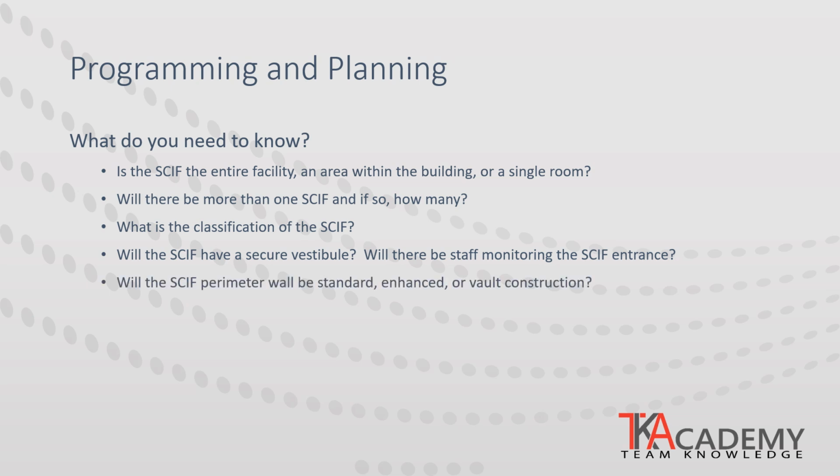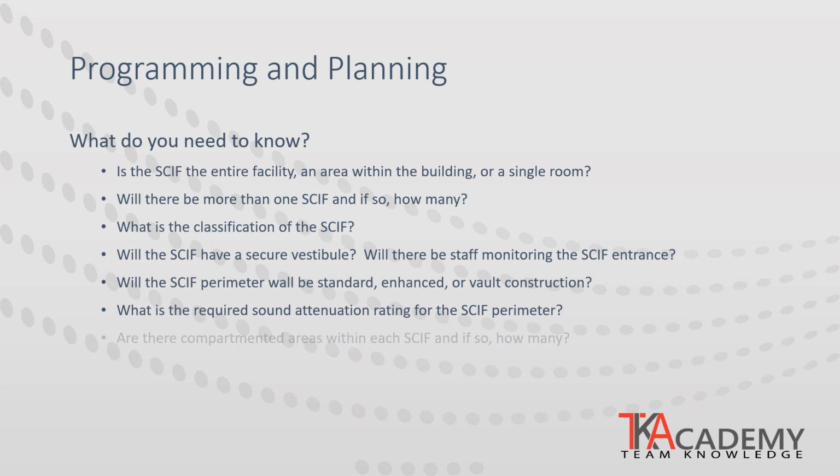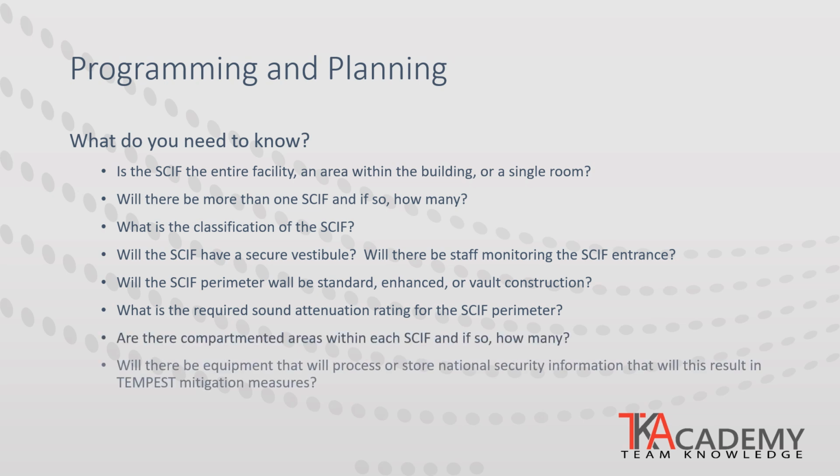Will the SCIF perimeter be standard, enhanced with RF shielding and wire security mesh, or vault construction? What is the required sound attenuation rating at the SCIF perimeter? Are there compartmented areas within each SCIF, and if so, how many? Will there be equipment or networks that will be processing national security information that will result in Tempest mitigation measures?